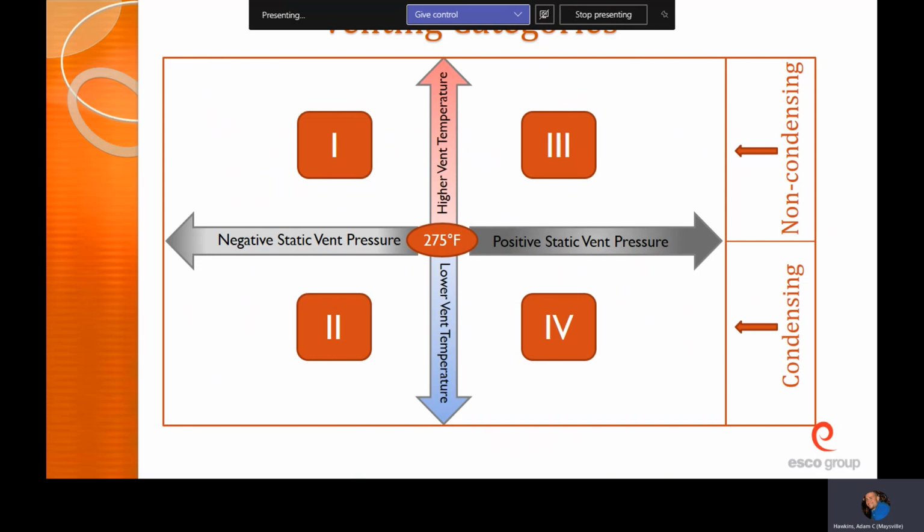It's because you're going to produce water. And if you have a metal vent and you have water, another thing is that water vapor is potentially slightly acidic, and so it will corrode a metal pipe like crazy. So not only just because it's water, but because it is corrosive, because of the way that it goes through the combustion process. So that vent has to be PVC, and it has to slope back toward the furnace so that any water that is collected in it is going to make it back to your drain. A condensing furnace has its own drain.